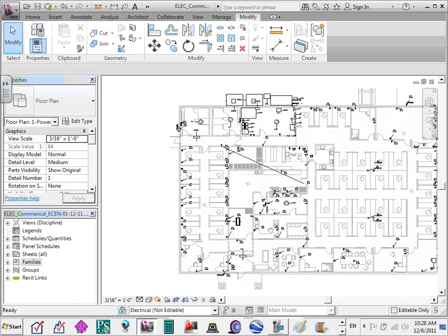Can you guys see at the top? You can cut. If I have a drafting view and I want to start drafting a riser, that's where it becomes very handy. You want to chop, cut, trim, modify, distance. All these things came in very handy if you are using Revit as a CAD. That's a Revit as a CAD component. I'm sure it has a lot of application in Revit too, but that's what we use it for.